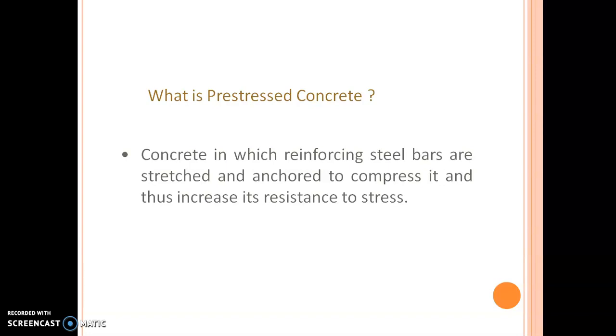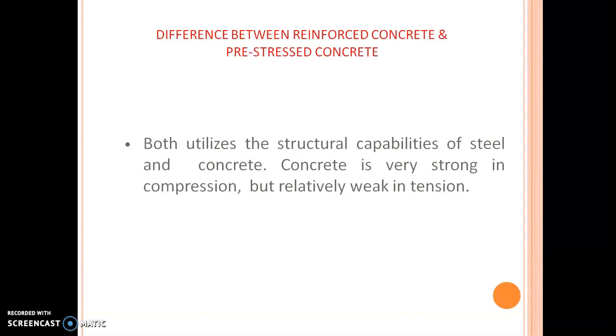But in reinforced concrete structures, as we all know, the reinforcing bars will not be stressed. Even before applying load, the stress in the reinforcing bars normally will be zero. So what is the difference between prestressed concrete structures and reinforced concrete structures? As I told, both have similarities. Both have a concrete section and both have some type of reinforcement. This reinforcement is to take care of the tensile forces while applying load, because concrete is weak in tension and stronger in compression.